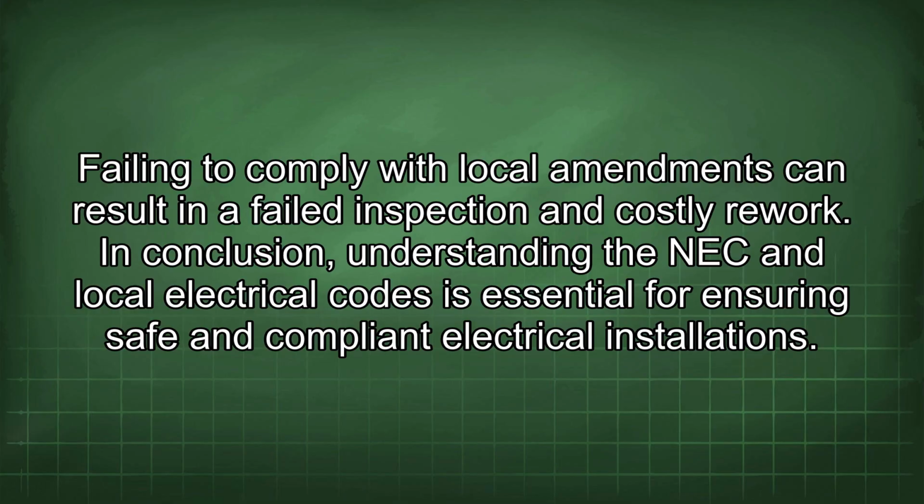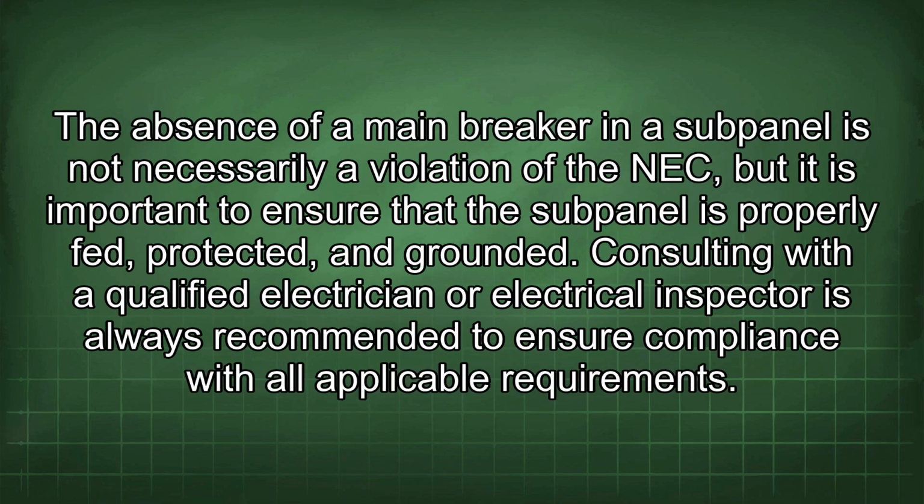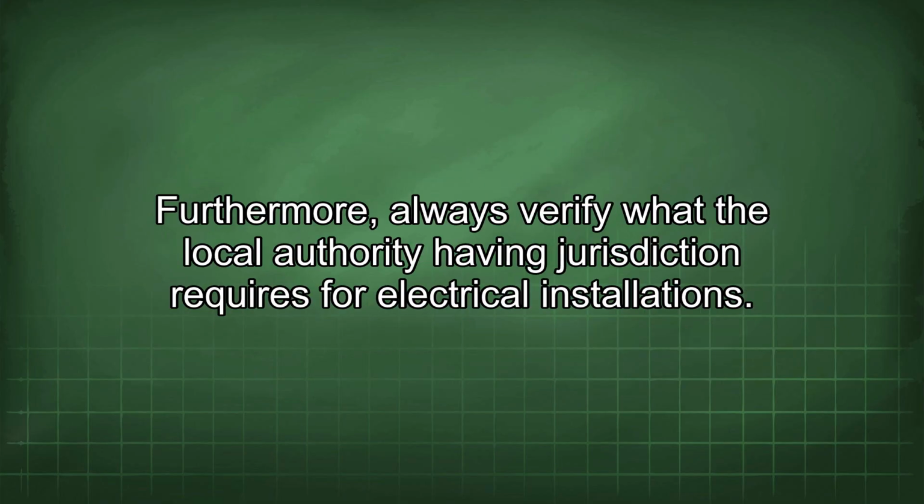In conclusion, understanding the NEC and local electrical codes is essential for ensuring safe and compliant electrical installations. The absence of a main breaker in a subpanel is not necessarily a violation of the NEC, but it is important to ensure that the subpanel is properly fed, protected, and grounded. Consulting with a qualified electrician or electrical inspector is always recommended to ensure compliance with all applicable requirements. Furthermore, always verify what the local authority having jurisdiction requires for electrical installations.